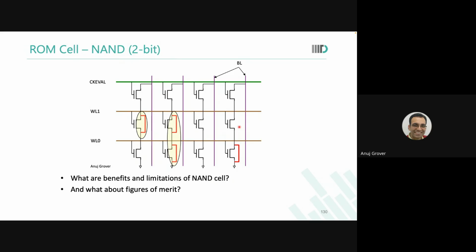So here I have shown just a 2-bit cell, so only one combination was possible. Consider I say that there is a 4-bit cell. 4-bit cell means there are 16 NMOSs in stack. Are you with me? Not 16 in stack. 4-bit means 4 in stack. But there are so many NMOSs in stack. Now all the combinations you have to see. And all those are variations in your read current now, over and above the device variations that are anyways going to be there.